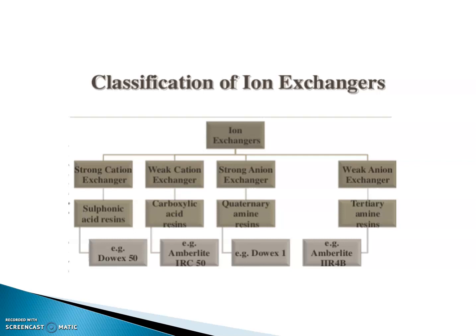In a full demineralization system, the use of weak acid cation and strong acid cation resin in combination provides the economy of the more efficient weak acid resin along with the full exchange capabilities of the strong acid cation resins.